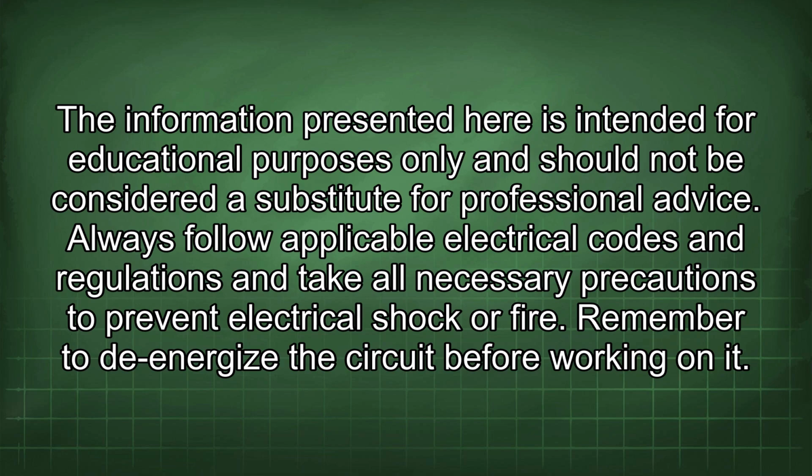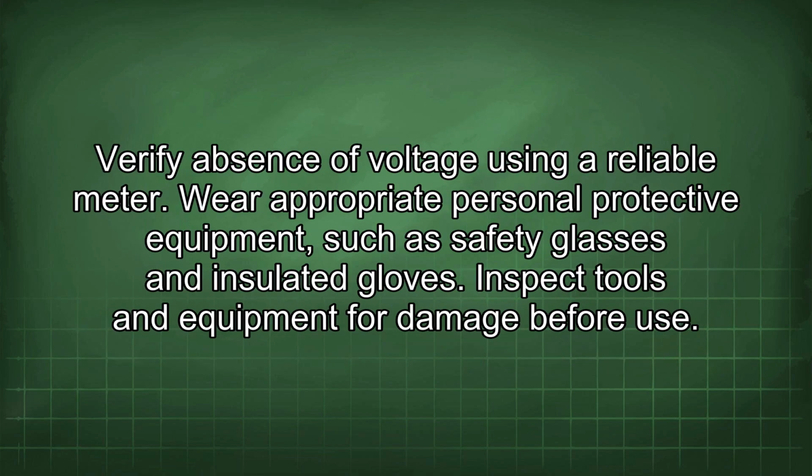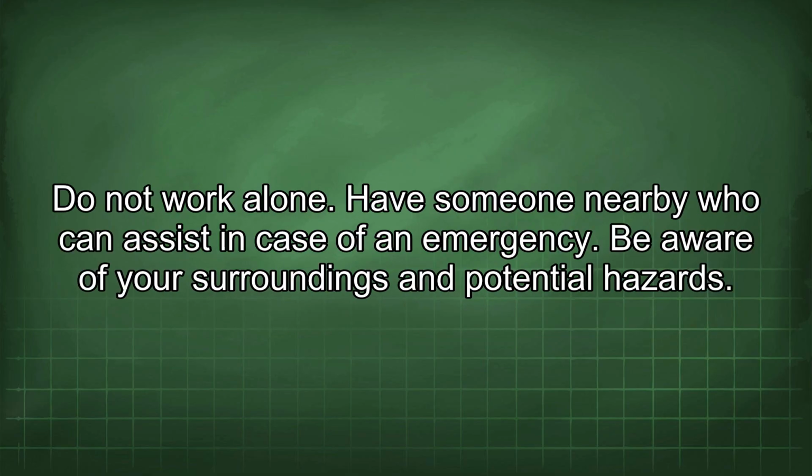Remember to de-energize the circuit before working on it. Verify absence of voltage using a reliable meter. Wear appropriate personal protective equipment, such as safety glasses and insulated gloves. Inspect tools and equipment for damage before use. Do not work alone. Have someone nearby who can assist in case of an emergency.